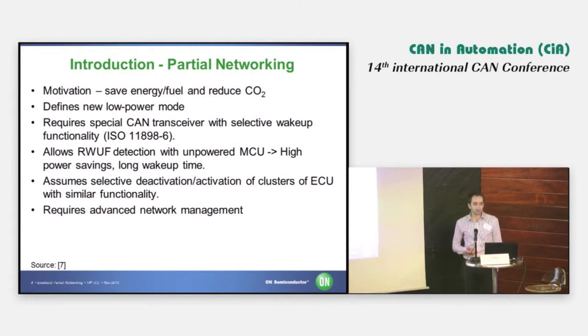While a standard CAN transceiver will interpret any frame or any communication on the bus as a wake-up event, this partial networking transceiver allows staying in a low-power sleep mode, or staying asleep, even if there is ongoing communication on the bus. So it helps to increase the low power running time, and the consequences are quite clear, I believe.